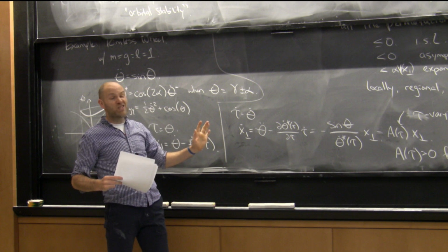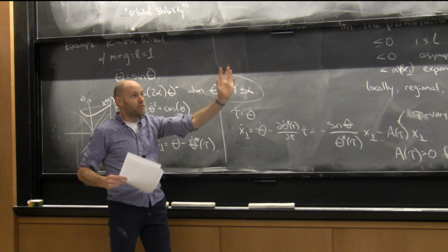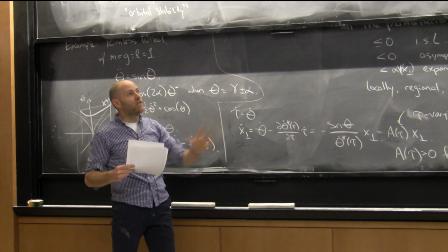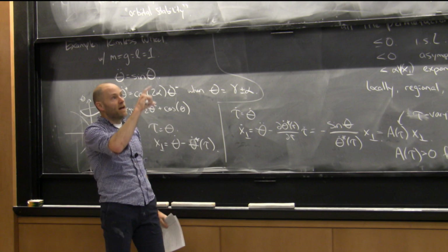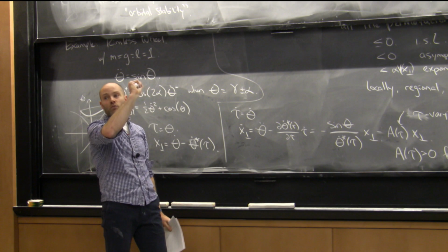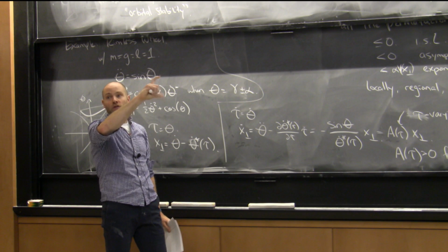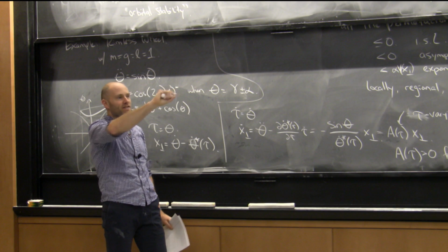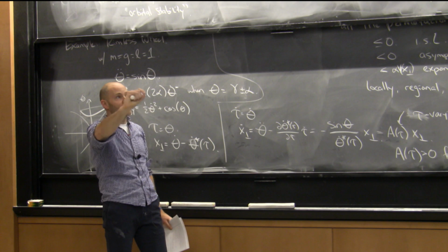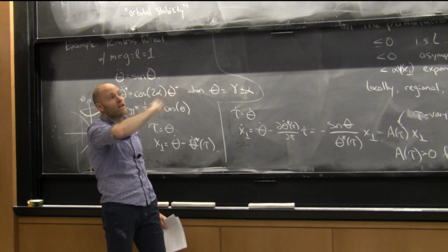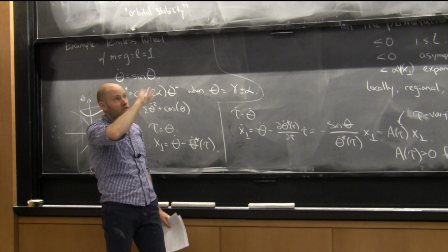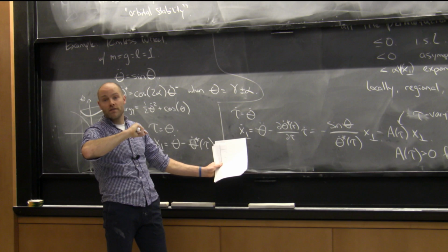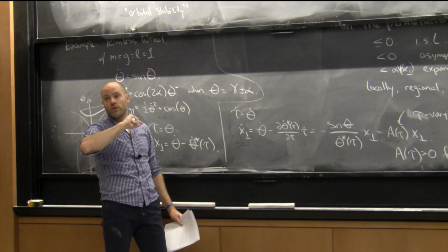Typically, we cheat a little bit and sample over time and just verify the condition at a finite number of times, because the dependence of V on time is typically complex and requires very high degree polynomials to capture it well. I'm okay sampling over any one dimension. Sampling in high dimensions sucks, but sampling along one dimension is okay. So those lines are actually where we sampled that. And we ran sums of squares, given the equations of motion in the transverse coordinate, in order to come up with that region of attraction.